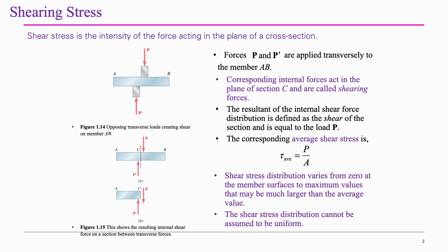Let's look at the second figure below now. This diagram illustrates how we can conceptually cut the member at some section C to analyze the internal shearing forces. In subfigure A, we show the cut with internal forces P and P' maintaining equilibrium. In subfigure B, we flip one half to show how the internal shear force acts in the opposite direction to the applied external shear forces. This is how we determine the internal shear force at a section.